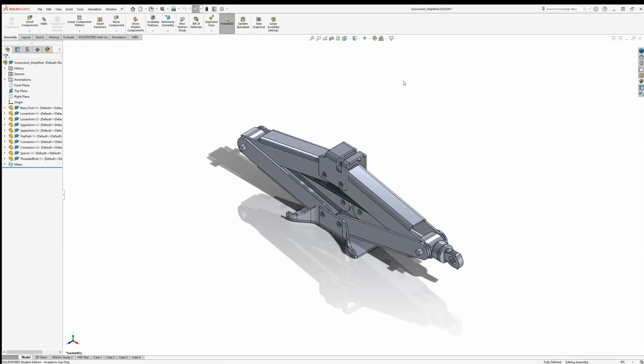A couple notes worth mentioning very early on, so don't worry about having to memorize all this. When you create these, the SolidWorks assembly file doesn't just copy the information into itself, because you'd think if it did, I'd end up with very, very large assembly files. Instead of copying, it basically finds references or paths. It stores the location of the part file, and that way it can go find that information and grab it as needed. That is a very important thing to understand as you start working with assemblies.